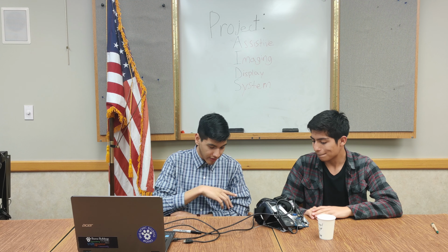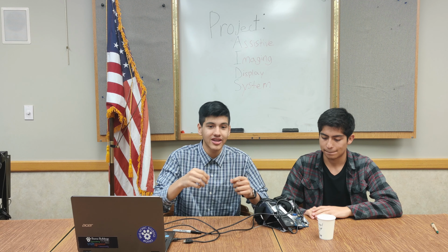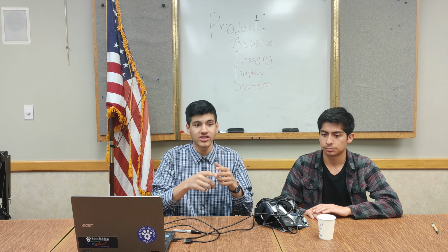Going more in depth on his explanation of the dot matrix, what we plan to do is make this system called EMU, or Environment Measurement Unit. What this does is, as he said, display a bunch of IR dots. Now, most cameras won't pick it up in a lighted room, so we're going to use an infrared camera to see where those dots are, and using some basic trig, we'll be able to calculate the distance of where those dots are hitting.